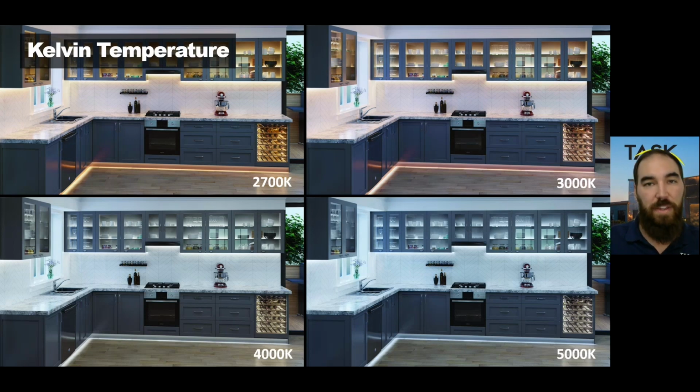Another thing before I move on, another thing I want to talk about is dimming. I think that if you're familiar with lighting, you've seen dimmable lighting before, but I think it's also important to know that when the lighting wizard drops lighting in, it's always going to drop in some kind of control mechanism that is capable of dimming the lights. So that's a given pretty much on any layout that you're dropping into, right? When you're using the design, the lighting wizard and things like that, you're always going to get some sort of control with the dimmer option included. So that's really, really handy to know.